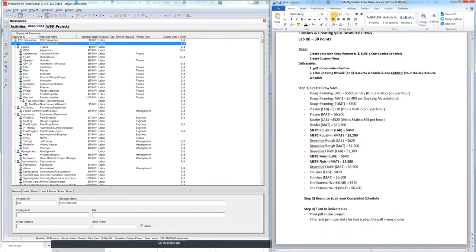I'm giving you all these rates right here. So where am I getting these rates? Yes, I'm making them up a little bit, but not really. This is based on my last project. Let's say rough framing materials. A lot of times your framer is a great example, will break out these three different cost codes: labor, material, and equipment. They do this because they want to get retention off of, let's say, the material, since they're paying that up front. A little different than your labor. But anyways, they're really easy to figure out.